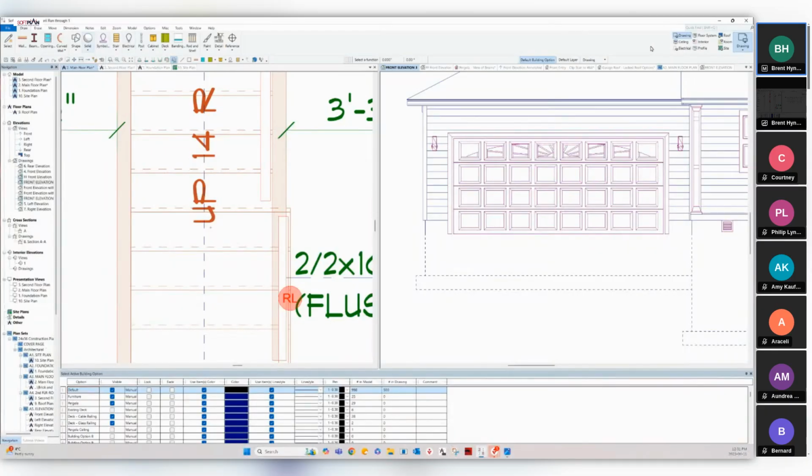You can go to Draw Shape Line, or pick it off your toolbar here, and use your F11 to snap to the end point of that line, and just drag it out. At that point, you can edit that, make that whatever thickness you need, and drag that across the entire width. I usually make mine about 1 inch to 2 inches and solid.